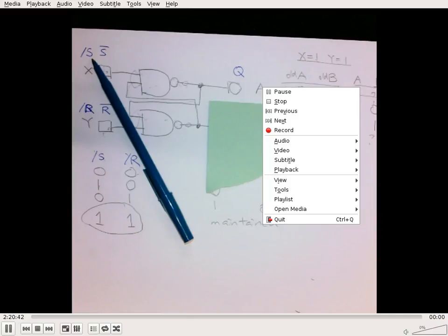What happens when the transistor turns on? It becomes a short, right? It is as if you're just connecting this line to ground. So when you have this line connected to ground through the transistor, remember this is a very weak pull-up. In other words, it's a very weak spring, barely hanging onto something, so that it's not all the way to the ground. So this is weak, this is strong. That means this line will no longer experience VCC. Instead, it will experience 0 volt, which is ground. That's how you trigger a reset.